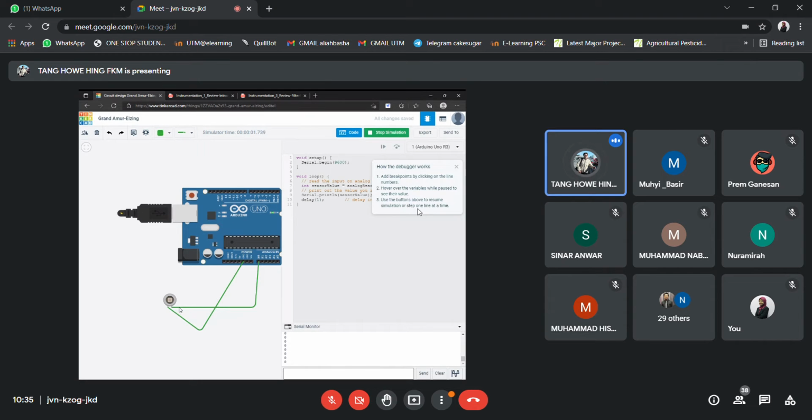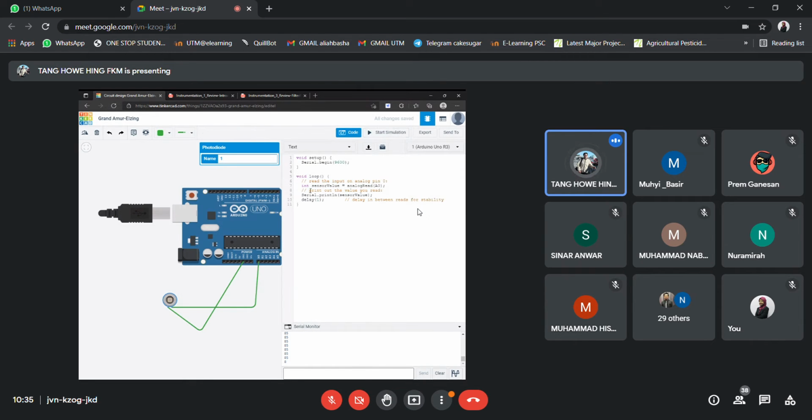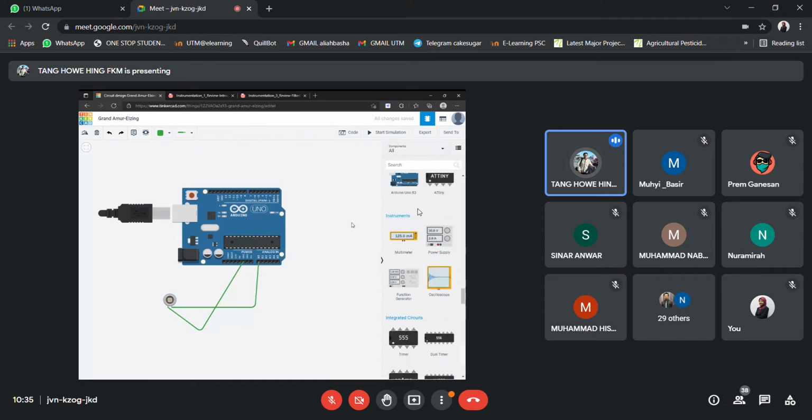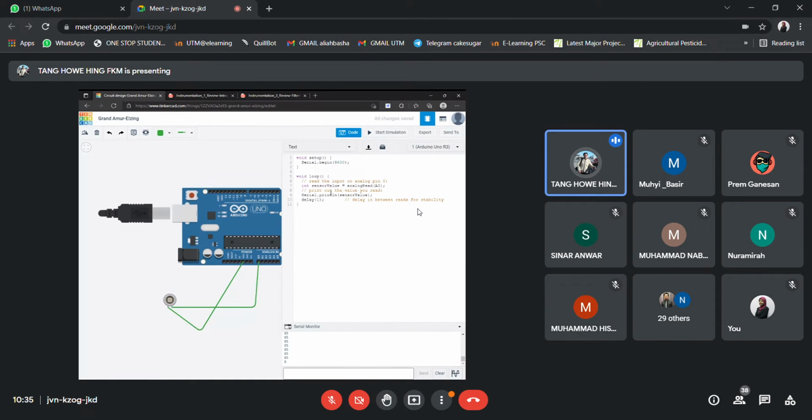The reading is initially 0, and then if let's say I keep on moving up, what I'm going to get is 85. Okay, so 85 just means that it is 85 out of 255. 255 stands for 5 volt, but we need to make some kind of calibration. So let's say this is a float. Okay, instead of integer, I'm using a float.